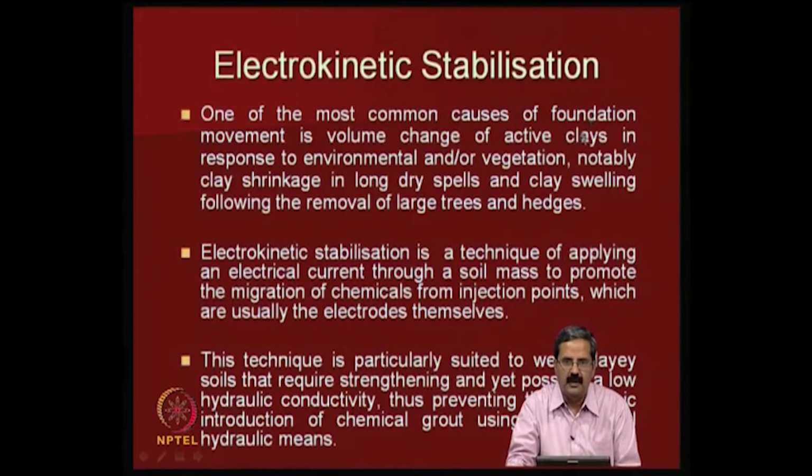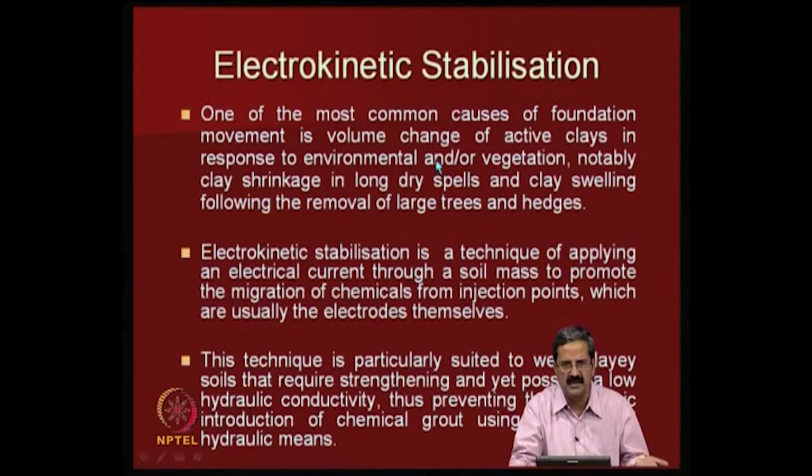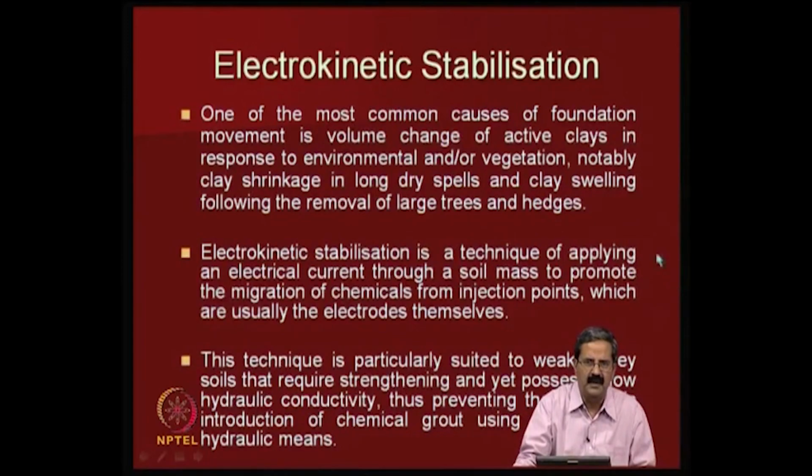One of the most important causes of foundation movement is the volume change of the active clays. For example, the bentonite clay, or expansive clay, or any general clay, soft soil has a lot of issues, particularly in the presence of environment. Like for example, if there is a water content change, there is a lot of swelling. It imbibes water, there is a water content change, and there is a swell. So many of these clays have a lot of difficulties, particularly shrinkage and volume expansion and all that.